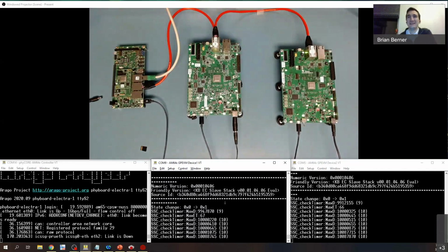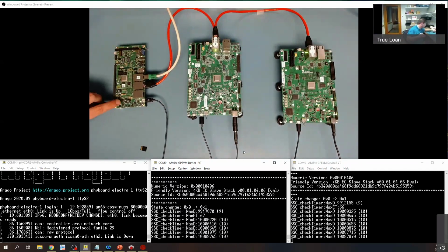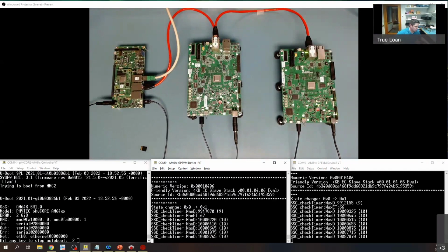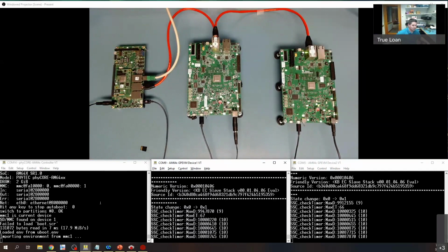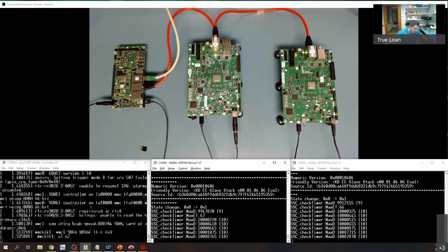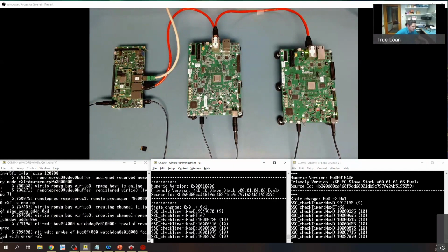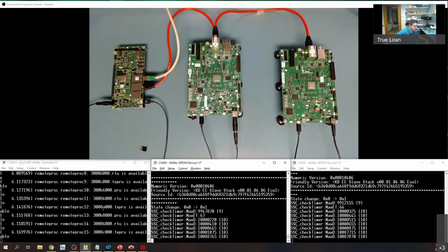While we've got the EtherCAT stack restarting, I'm going to boot up the main board, and again, this is just the Linux board, with a Linux SD card that I provisioned with the CodeSys runtime again, but this time I pre-built an EtherCAT network off screen. So again, it's a very similar process to what we saw with Profinet.